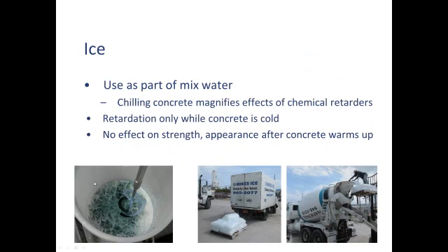So when you use it as part of your mix water, it's added to your ingredients as part of your mix water. So you put it in your bucket, you put your ice in, you add the rest of your mix water, and let's say you needed 3.7 kilos of water. You might start with a certain amount of ice, add that to your bucket, and bring the remaining up to the proper amount of water.